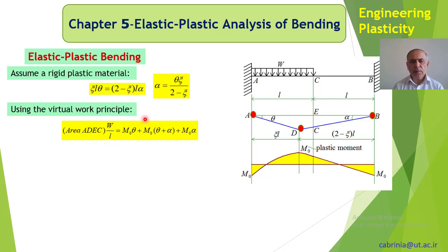Now, what causes this virtual work is the internal work. This virtual work, in fact, is equal to the internal work. What is the internal work? It is the moments we have taken here. M0 is the plastic moment, the complete plastic moment here and there. So here M0 is moving this link, so M0 times theta. Theta is the angle. Here we haven't taken the angular speed because we are not using the power or rate of work.